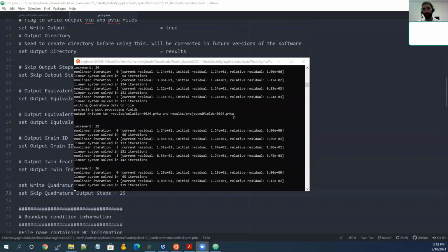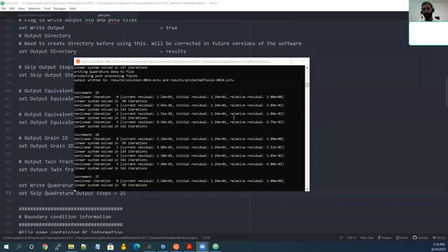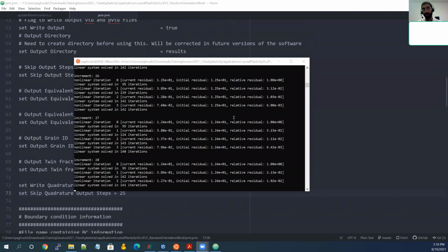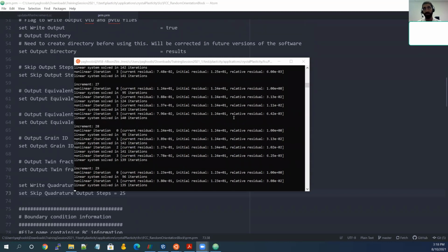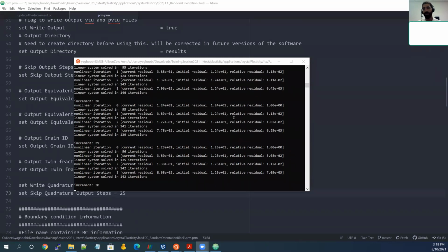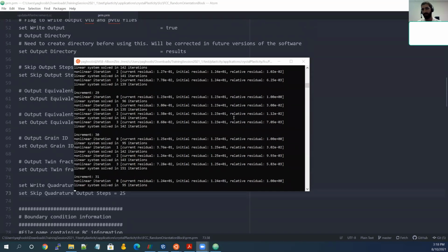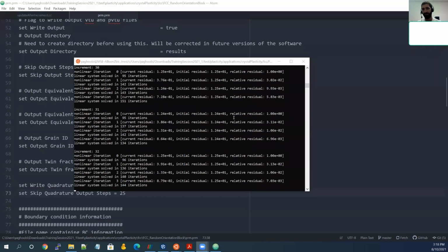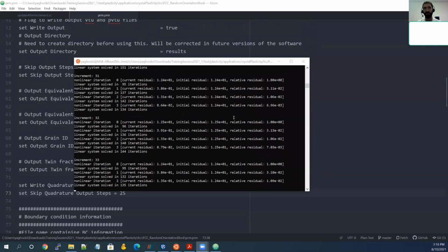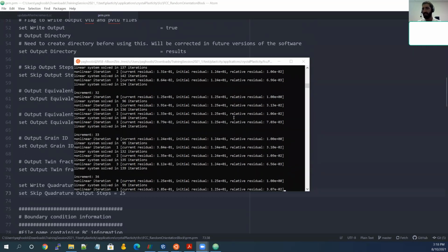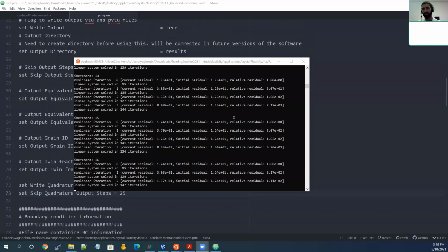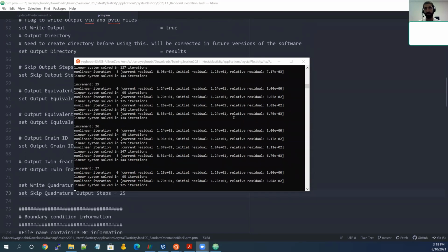Another one is if you want to use, for example, a 7 by 7 by 7 mesh, you cannot refine that in any way by set refine factor. So then you have to go with the subdivisions. If it's neither of the cases, it's always better to start with 1, 1, 1 subdivisions and use set refine factor.